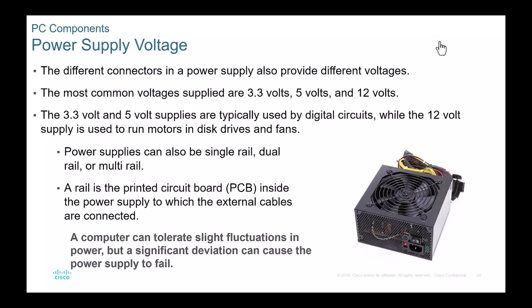Different power supply voltage. The most common voltages that you're going to see are 3.3, 5 volts, as well as 12 volts. Your smaller voltages tend to be for smaller components or smaller chips, whereas your 12 volt is going to be more for anything that has a standard disk drive, like the old school regular hard drives, the non-solid state ones, your fans, and a lot of your fan controllers.